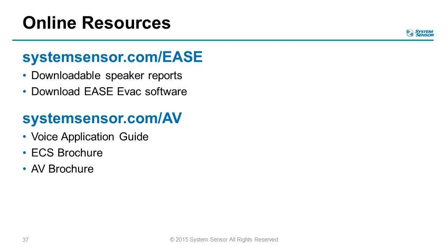I just wanted to summarize real quickly everything that we talked about here, just to close things up. Obviously, NFPA 72, the 2010 edition, really did incorporate a lot more information on intelligibility within the body of the code, just so that everyone's aware of that. Prior to that, most of that information was in the annex, so it wasn't necessarily required. It was more of a, here's how you might want to do it, but it wasn't required. As more states are going to the latest edition of the code, you may be required to meet it, and you might have to actually measure it. So it's a big, drastic change for fire alarm and voice evacuation systems.